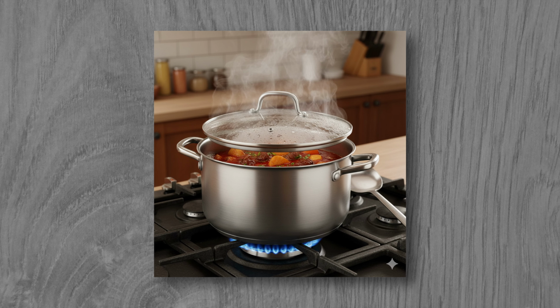Reducing indoor humidity levels is essential for minimizing condensation risks. One effective method is using dehumidifiers, which extract excess moisture from the air, especially in high humidity areas. Another approach is adjusting HVAC settings by running air conditioning or using a humidistat to help regulate indoor moisture levels. Additionally, limiting moisture-generating activities can make a significant difference. Simple actions such as covering pots while cooking and running exhaust fans during showers can effectively reduce indoor humidity.